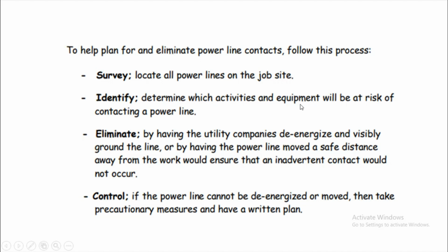And also for the equipment, we can check, for example, the height of the equipment that needs to pass under the overhead power lines. You can identify the height of the equipment, and whether it complies with the minimum clearance above the topmost part of the equipment. Otherwise, change the equipment or don't pass that way.